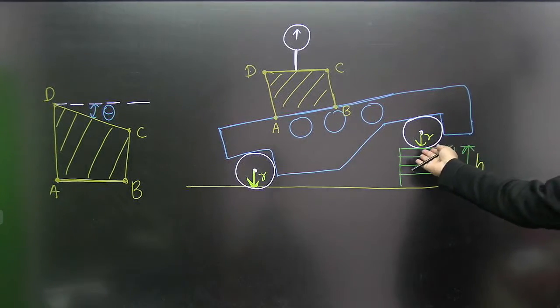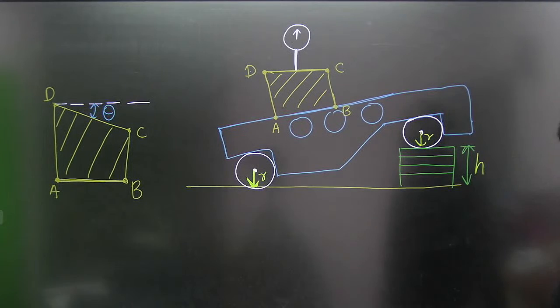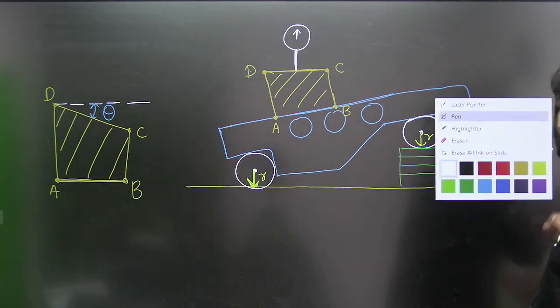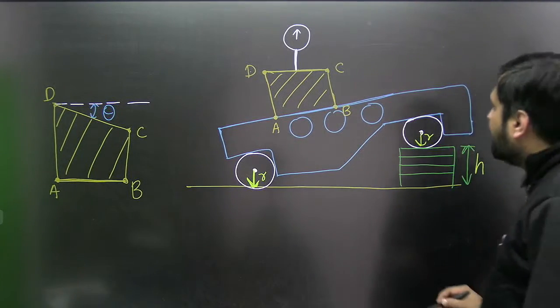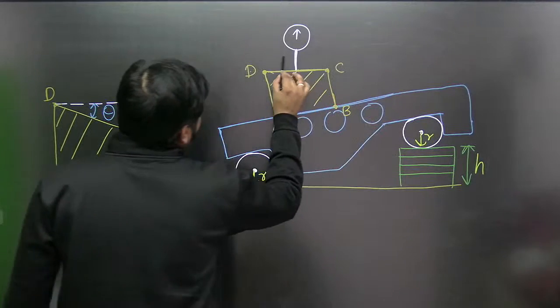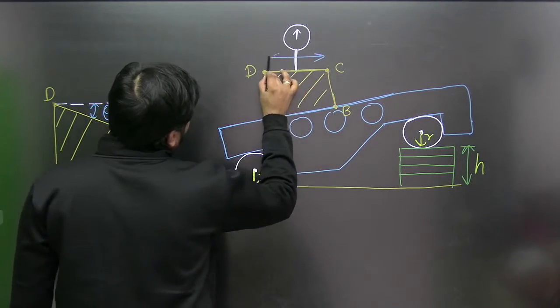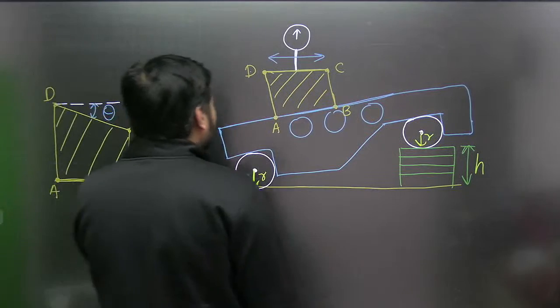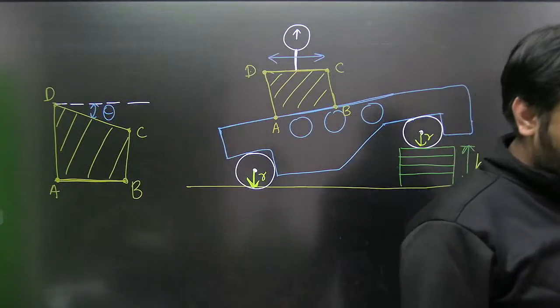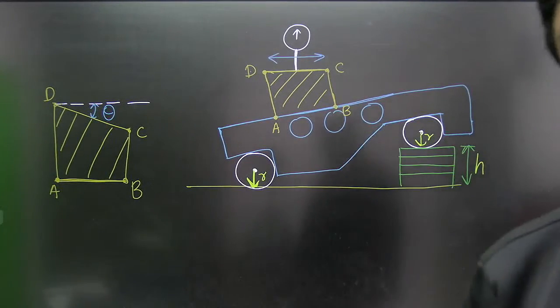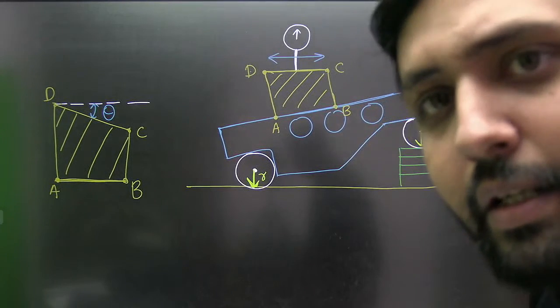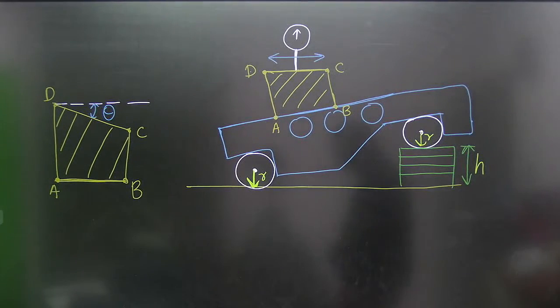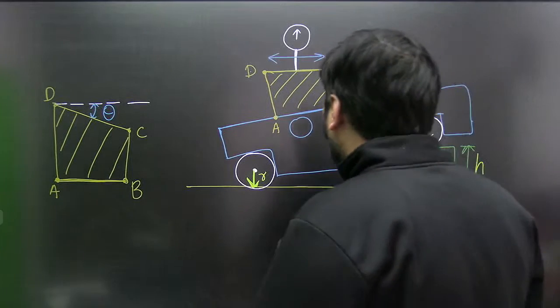The sine bar is getting the tilt upward, and meanwhile we'll move this dial gauge left and right over the surface CD, from C to D, from D to C, to check whether the needle is getting certain amount of deflection or not.